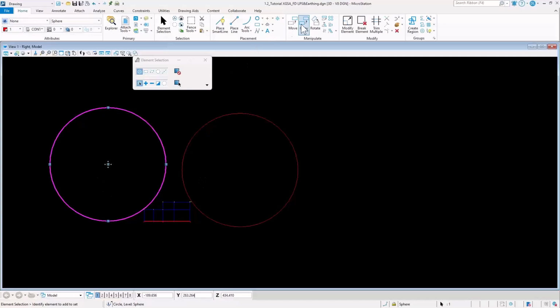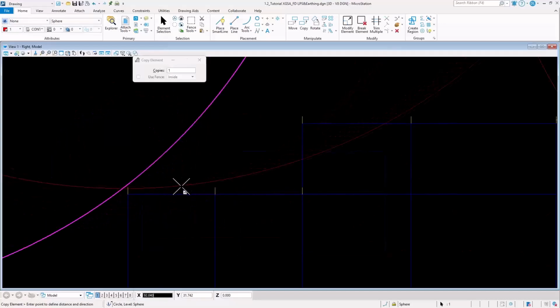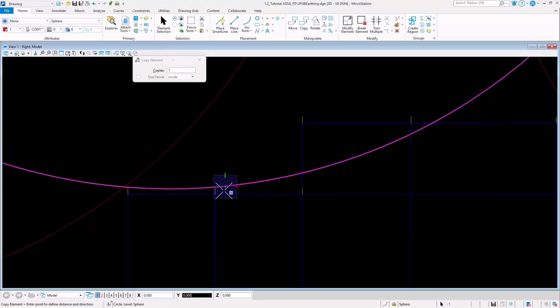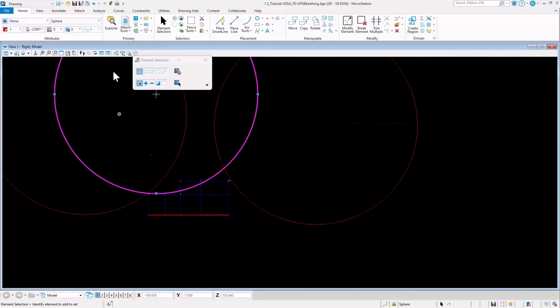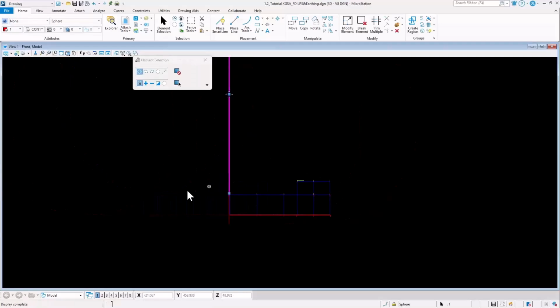And what I can do with this is I'm just going to copy this value. And I can look to see, as I move my sphere across my system, if it's making contact with the structure. It wouldn't do that because I actually have air terminals that will prevent that. And the air terminals are illustrated in orange here. Now I have my view from the right. We'll have to replicate this as we look from the front view of this system and roll the sphere over this way.